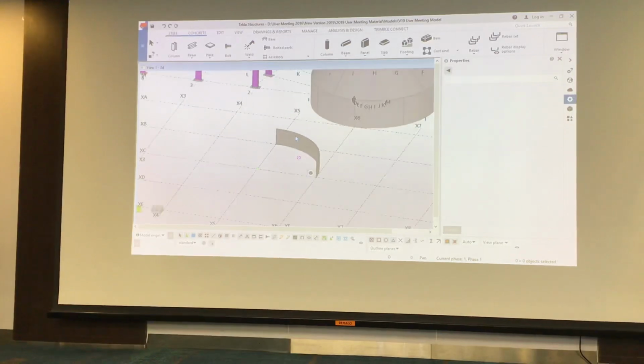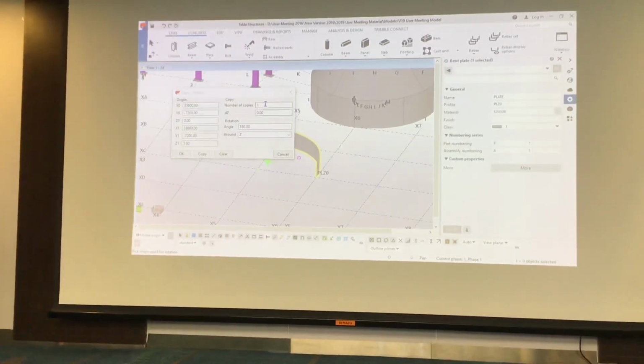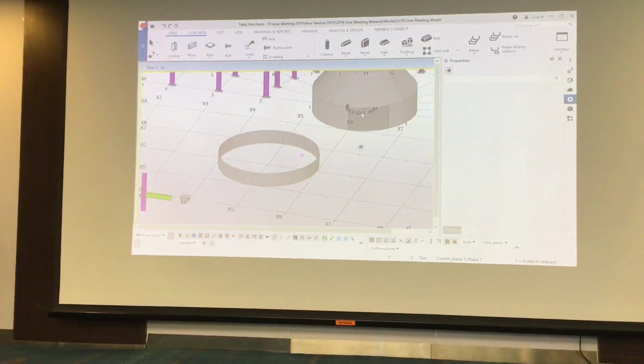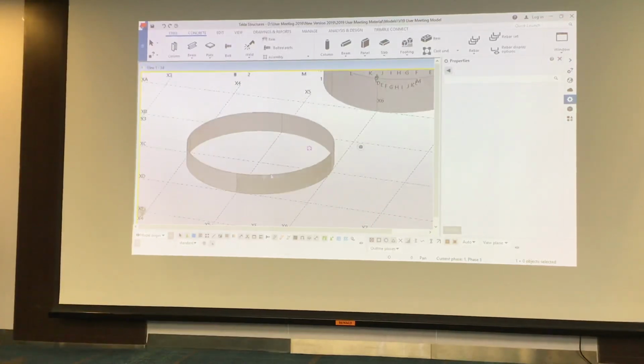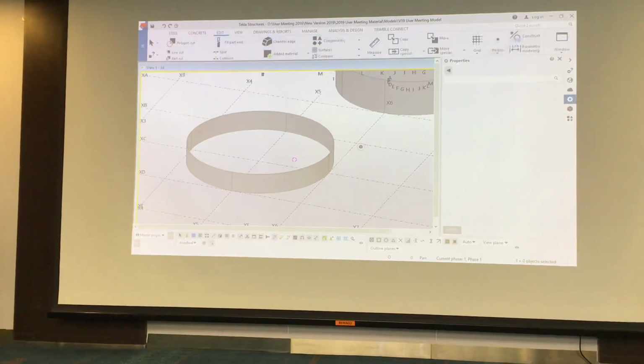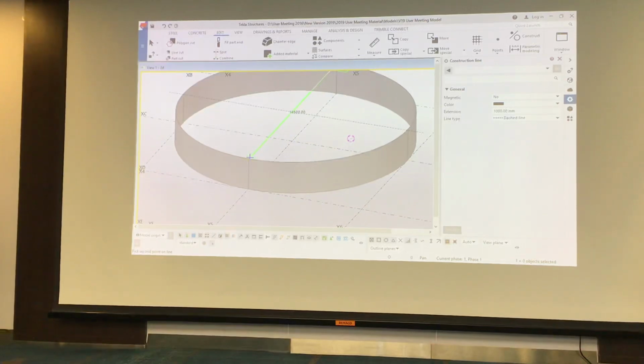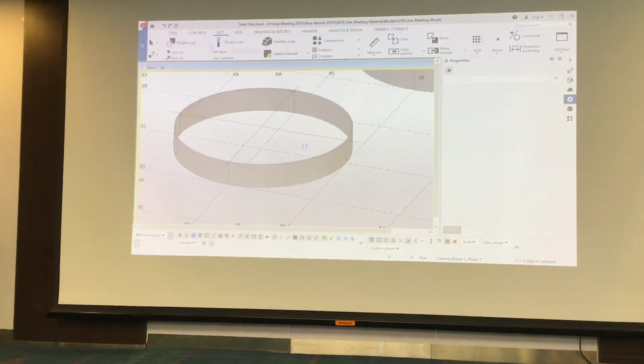That's really fantastic. But I'll pick that one up, and I'll say, let's copy that, rotate around that point, 3 copies through 90 degrees. So then we've made that whole shape, like I've done here, look. So that now is made from those points. I find that using construction lines now is the best way. So I'm going to say, okay, I want a construction line from, let's say, that point there to that point there, and a construction line from that point there to that point there. Right. Now I'm going to do that again.